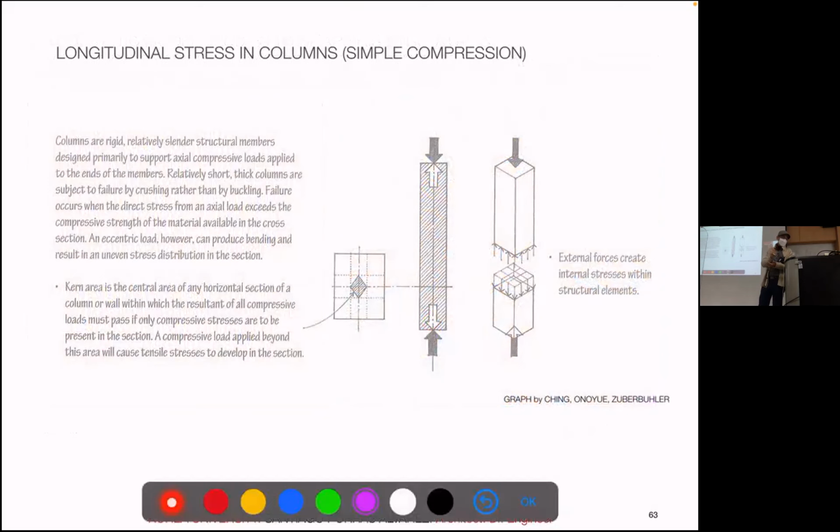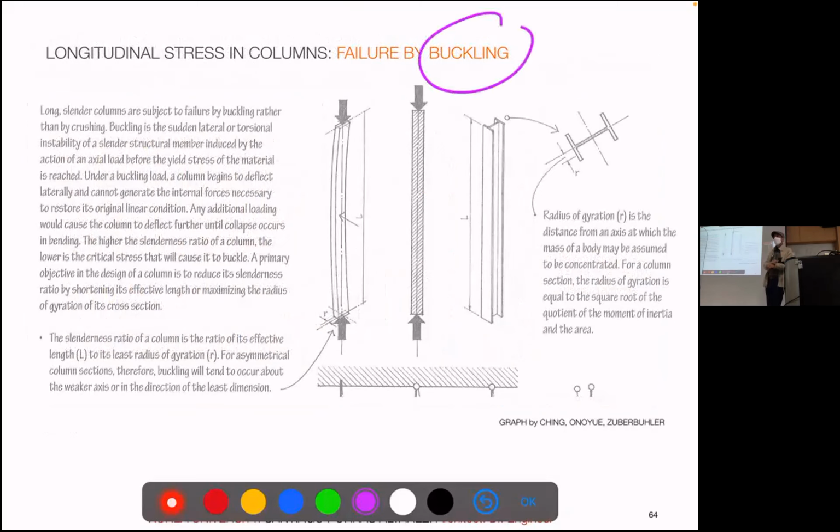So this is repetition. Longitudinal stress is very easy to understand. I will not go into it, but it's important to know about buckling. In those stone buildings, Gaudi is probably a bit at the limit, but still not so much. The stronger the materials we have, the more tendency they have to buckle, to bend, even if they are not at maximum stress, right? We know by experience it happens. And it's actually more acute in steel, because steel is very strong. So sometimes we have to dimension based on avoiding buckling rather than on the strength itself.